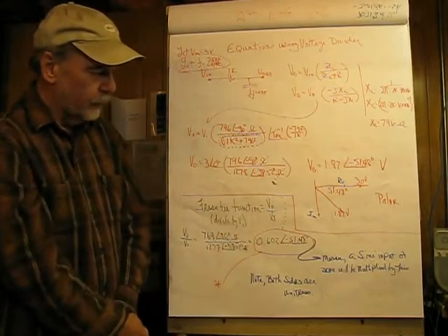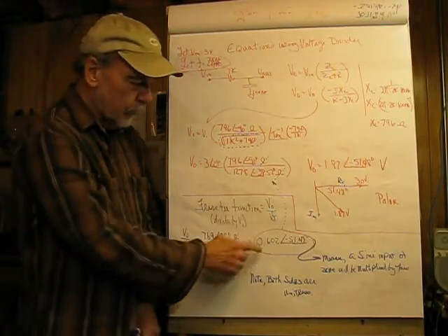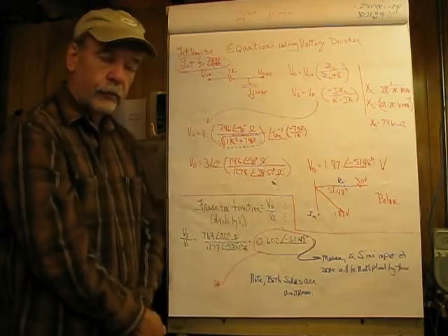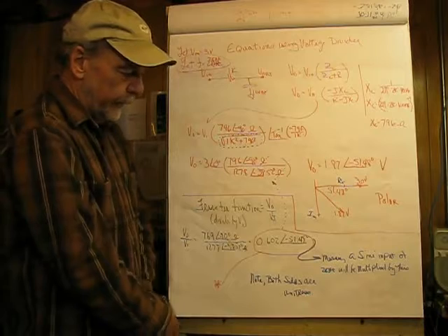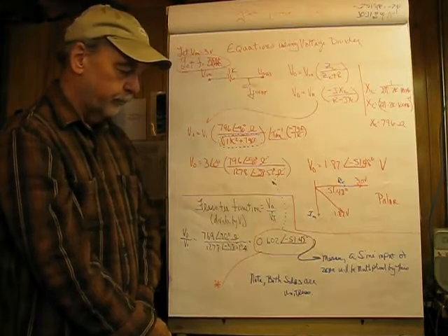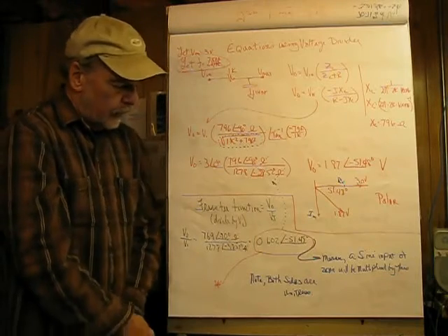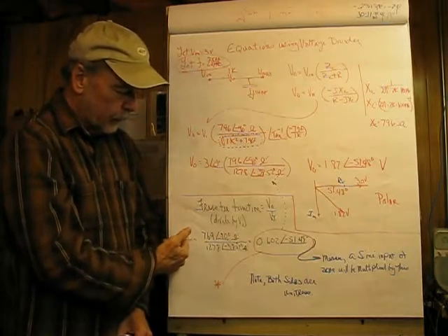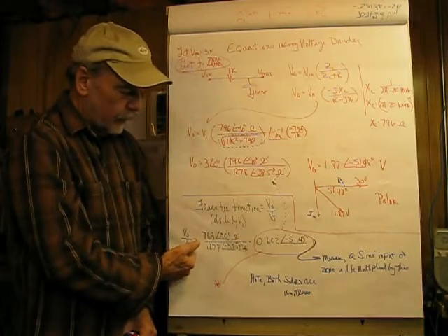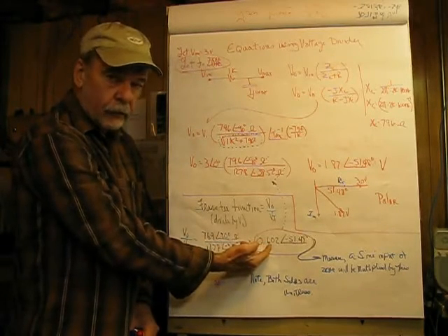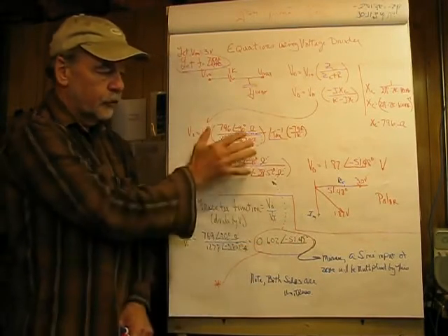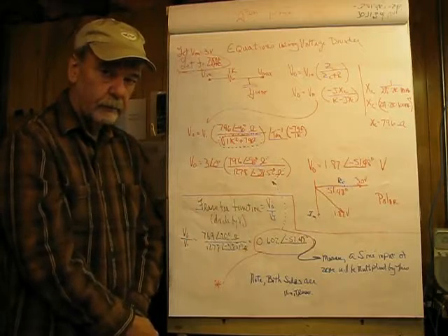is our 0.602, and that would be this divided by this, so that's pretty good, and it would have an angle of our negative 1.48 degrees. So putting that into English, if we took our output, we wanted to find output voltage, we would take our input and multiply it by this term, the transfer function, it would give us the same output voltage as we got by using voltage divider.